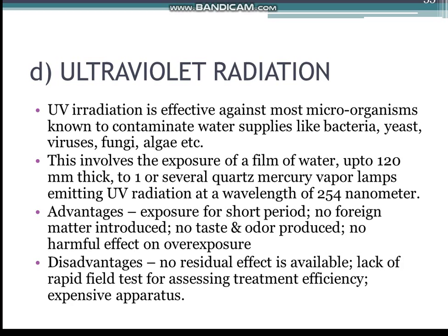Applications are limited to individual or institutional systems. The water should be free from turbidity and suspended or colloidal constituents for efficient disinfection. The advantages are that the exposure is for a short period, no foreign matter introduced and no taste and odor produced. Overexposure does not result in any harmful effects. The disadvantages are that no residual effect is available and there is a lack of a rapid field test for assessing the treatment efficiency. Moreover, the apparatus needed is expensive.